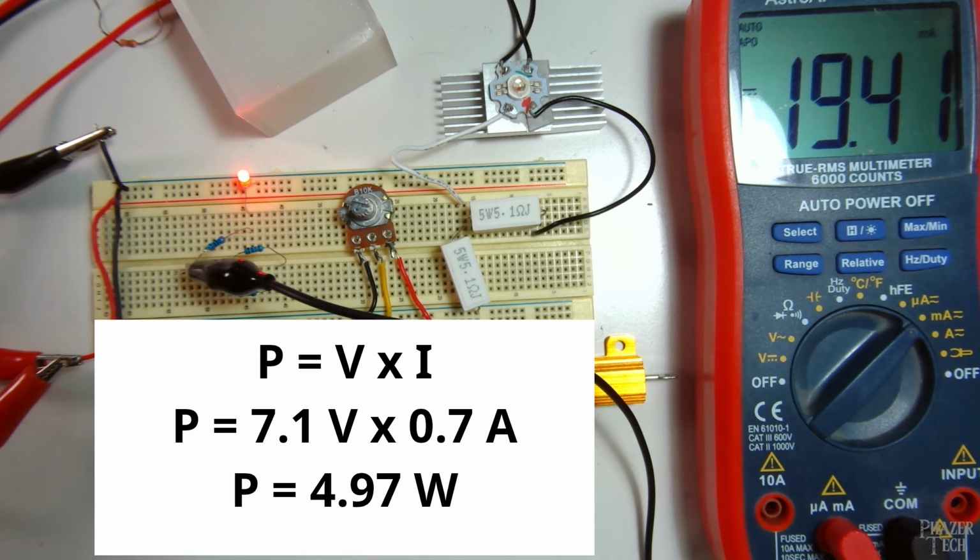Well, 7.1 volts times 700 milliamps equals almost 5 watts, which means our puny little quarter watt resistor would probably burn up and give a little fireworks show if we tried to use it. Of course, we don't have to put 700 milliamps through the LED. We could use the 360 ohm resistor and only put 20 milliamps through the LED, and the resistor would be fine. But then there's not really a point of using such a big LED.